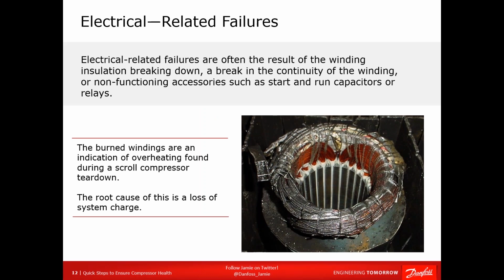So one of the first electrical failures, if you work in a teardown laboratory, you're going to see two main things. You're going to see something like this, where a compressor overheated and it burned up and it's black and it stinks. Back in the days of chlorinated refrigerants like R12 and mineral oil, you would actually get acidic vapor coming off of these things, fumes that would burn your eyes. Today, not so much. But you can see here, there's been a lot of damage. The other one you're going to see is the opposite. When the compressor kind of got too cool, you had liquid coming back, destroyed the lubrication, and the compressor seized.